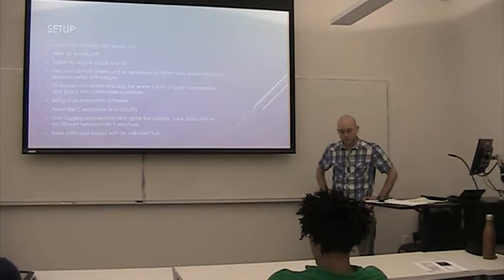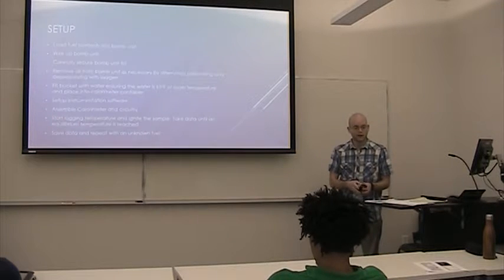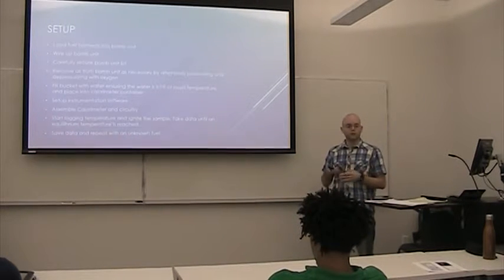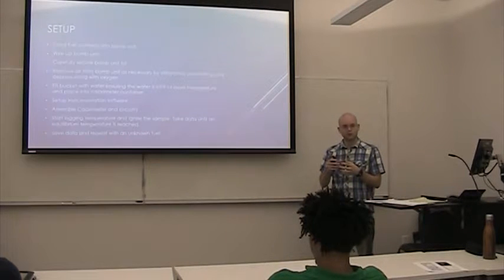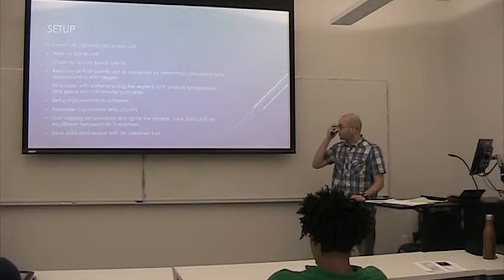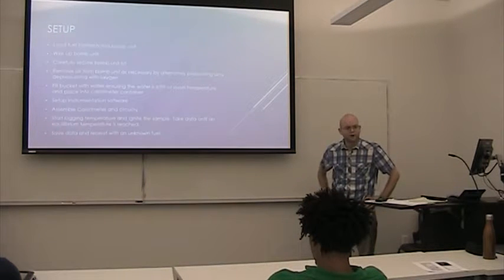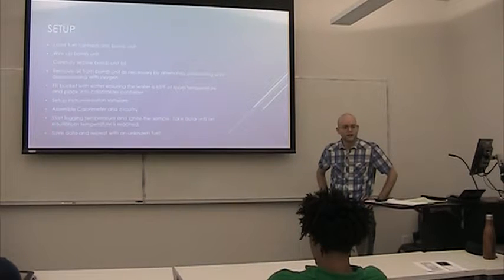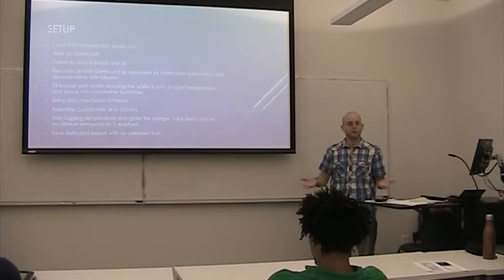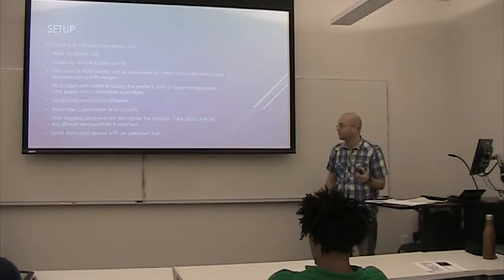But the purpose is to ignite the fuel sample. This is a constant volume calorimeter because we're going to keep the whole ignition process within an enclosed volume. It's not like a coffee cup calorimeter, where it's not sealed very well and it's open to the atmosphere. Some people ask, why do we use 2 kilograms of water? Why not more or why not less? In my opinion, it's really just because it's a known quantity. It's a standard practice number, something that we can easily quantify.